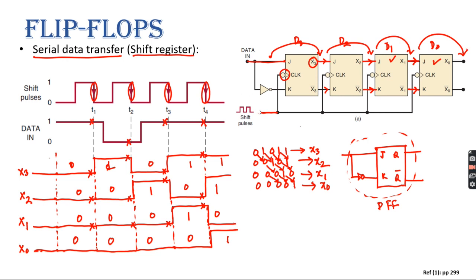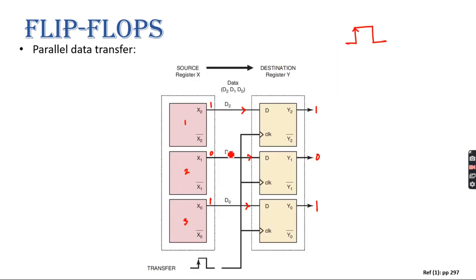Yes, sir. So that's why it is called serial data transfer, because in serial data communication, one bit is shifted at a time, or one bit is transferred at a time. If it is a parallel transmission, like the previous case, then you will have so many channels, and the number of channels will be equal to the number of bits that you can transfer at a single time.